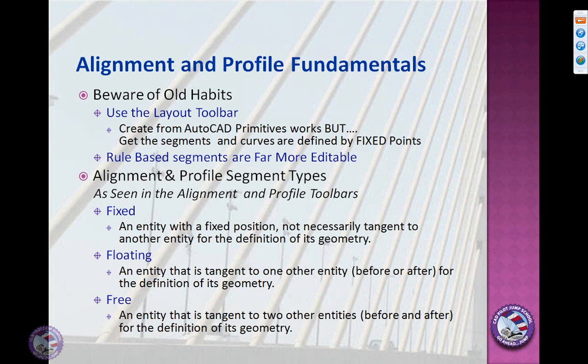So very often we'll be doing free, and it's sort of like the default inside of the way Civil 3D works. And there are a couple other defaults that are built into the way Civil 3D works, and you can control those defaults. So if you work in a jurisdiction that requires you to use asymmetric parabolics all the time because some civil engineer, George, thought that was cool, you could do so with a simple command setting in Civil 3D.